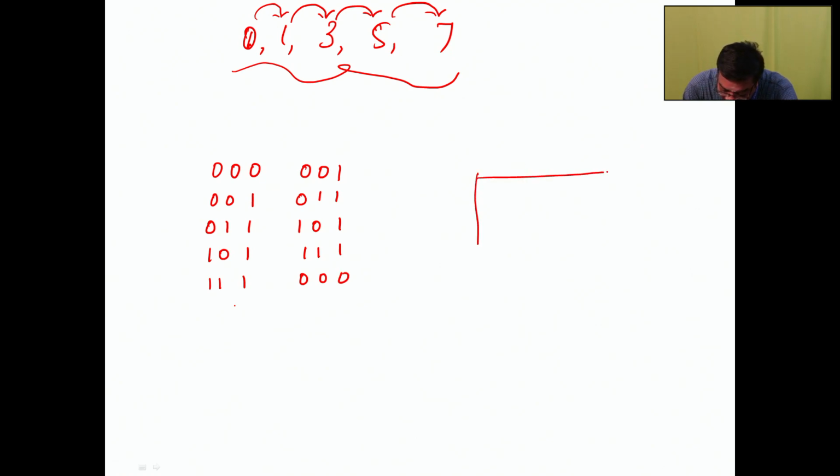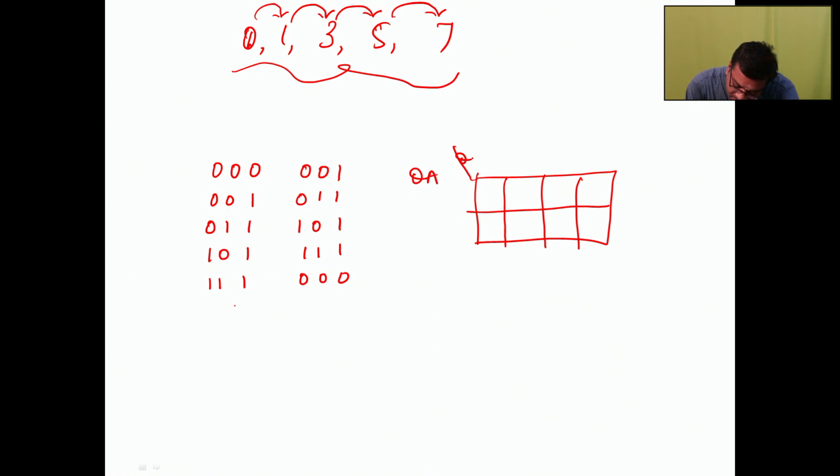While we are determining the K map, we are going to solve in QA, QB, QC: 0, 0, 0, 0, 0, 1, 0, 1, 1, 0, 1, 0, 1, 0, 0, 1, 0, 1, 1, 1, 1, 1, 0, that is 0, 1, 3, 2, 4, 5, 7 and 6. For 0, the next state is 1. For 1, the next state is 3. They have given these outputs. For all the other conditions they have not given any, so 2 will be don't care, 4 will be don't care, 6 will be don't care. All the others, the outputs will be determined. Like that we are going to solve the K map here.